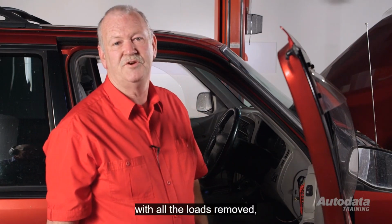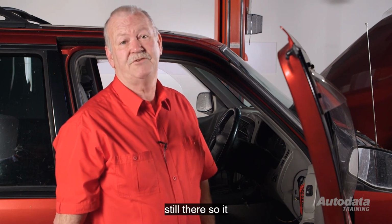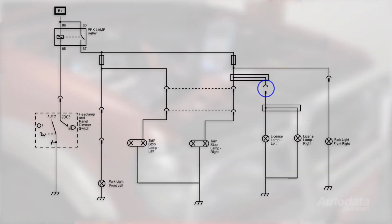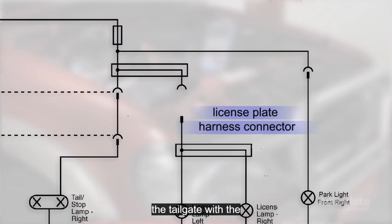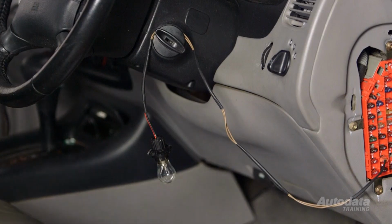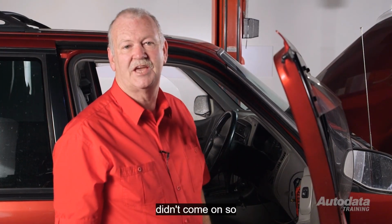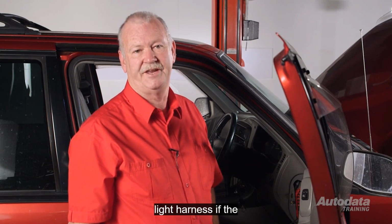With all the loads removed, the light's still bright, indicating the fault is still there, so it must be in the wiring. Unplugging the connectors in this circuit will isolate the fault. I'll start with a license plate harness connector in the tailgate. With the trim removed, I can access the connector that needs to be unplugged. This time the light didn't come on, so the fault must be in the right-hand license plate light harness.